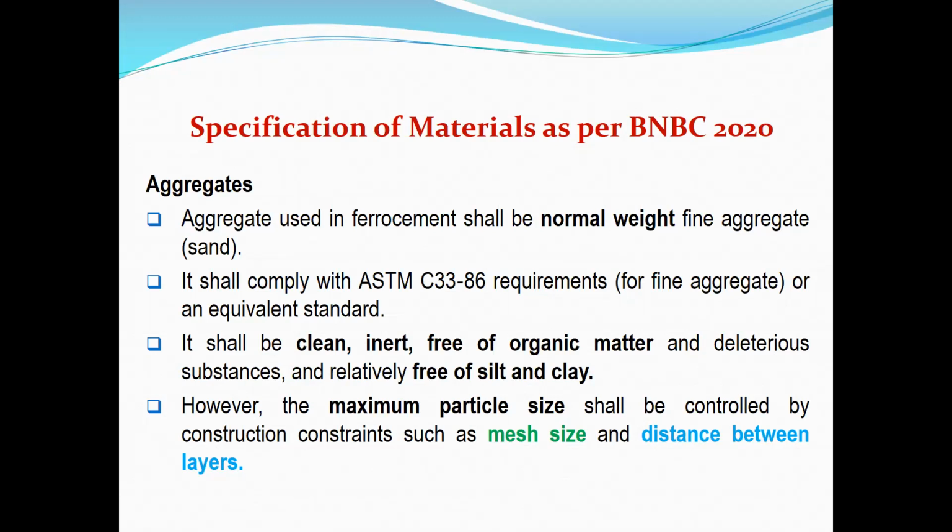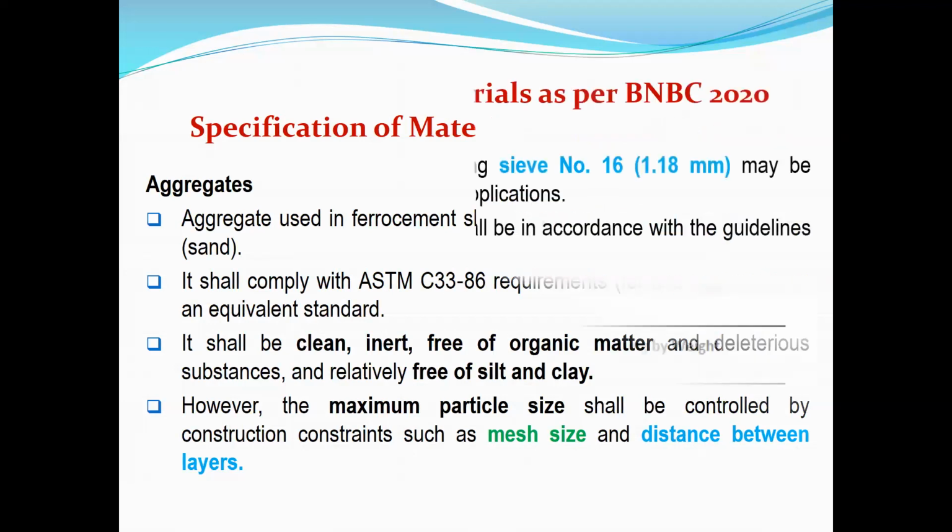The maximum particle size shall be controlled by construction constraints like the mesh size. The meshes are closely spaced, and you have seen that the rods are spaced from 1/4 inch to 1 inch. Various layers of mesh are used, and a distance is maintained between the various layers. Altogether, the thickness is 2 inch. So the particle size, that means the aggregate that you are going to use, is controlled by this mesh size and the distance between the layers.